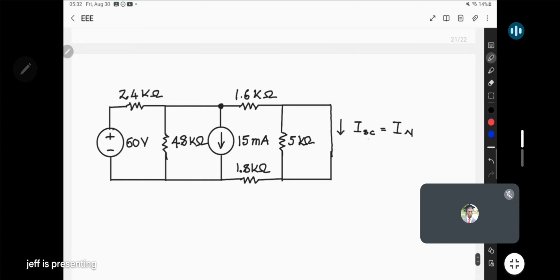So what does a short circuit in a circuit like this change? Well, it changes one thing. When current is coming this way, as it reaches this junction, it sees two routes. One route goes through the short circuit. The other route comes to pass through the 5 kilo ohm resistor. Now, current will always take the easiest route here. So one route has a resistor. The other route does not have a resistor at all. So in this case, current will take the route with no resistance.